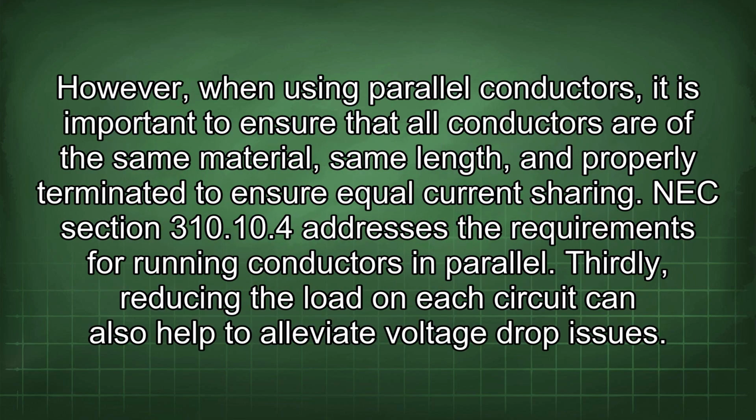However, when using parallel conductors, it is important to ensure that all conductors are of the same material, same length, and properly terminated to ensure equal current sharing. NEC Section 310.10.4 addresses the requirements for running conductors in parallel.